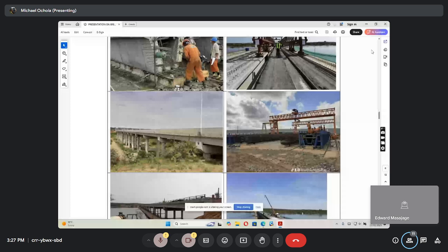You can see this is the contractor's supervisor. Before the inspector comes, the construction supervisor is already checking that this guy, the steel bender, is doing the right work. Here now they did the casting. These are the girders you see. These were T girders. We shall also learn about them, and we shall look at pictures later, not now. So these are T girders. Then from the T girders, they're precast, and you can see there's no formwork. So they form part of the formwork. It's designed to take care of the formwork because of these water bodies, and the spans are 40 meters.